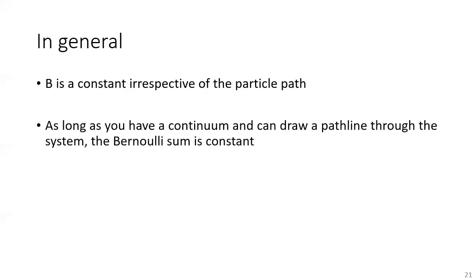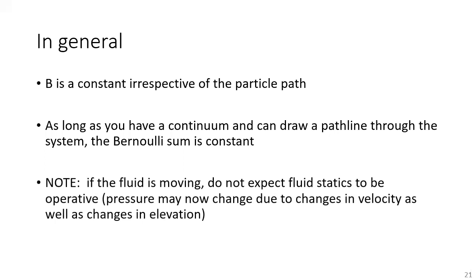As long as you have the continuum and can draw the path line between 2 points, the Bernoulli sum is a constant for now. Later in the semester, it won't be constant, and I will tell you that day. If the fluid is moving, do not expect fluid statics to be operative. What does that mean? Pressures can now change just due to the velocity itself. So before we said dp dx was 0. That's not true now in a moving fluid. We can have pressure changes, and I'll sketch that for you. We can now have pressure changes in the horizontal direction just because velocity changed.